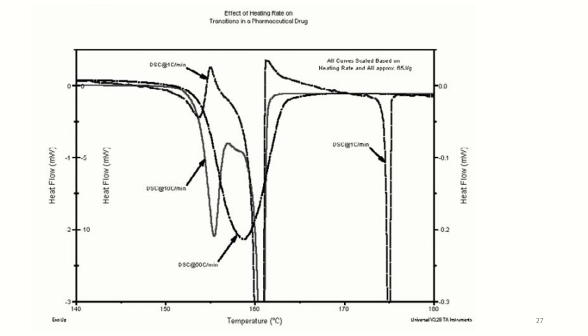One concern at high heating rates is the loss of resolution. So this is quite a disadvantage of high heating rates. The major benefit of the new modulated differential scanning calorimetric technology is the higher resolution, which is provided by the Tzero and heat flow signals, which account for the thermal lags that occur due to the sensors and pans.